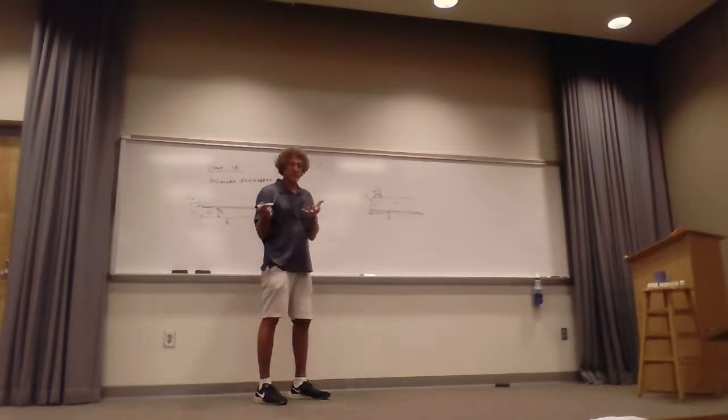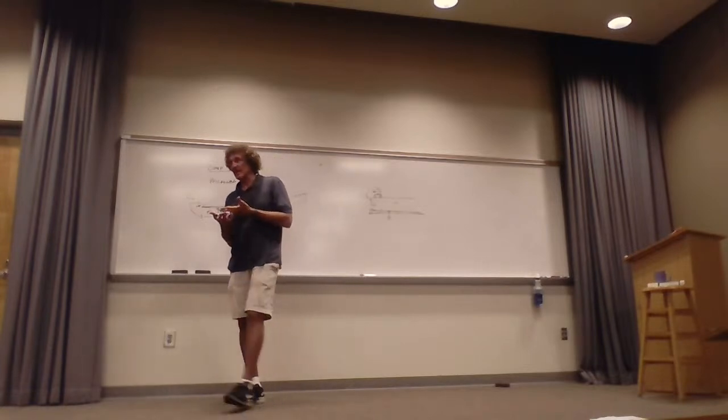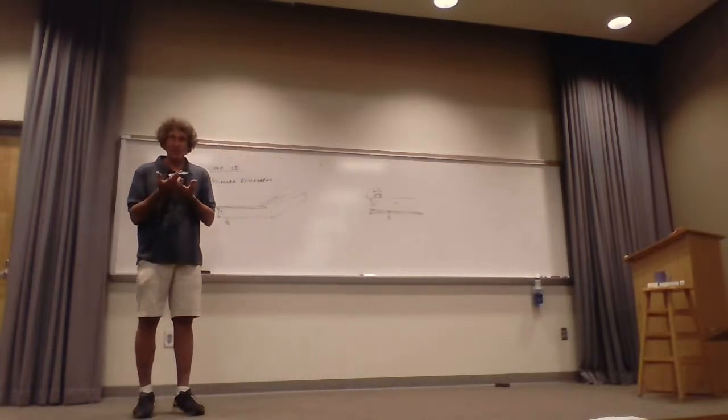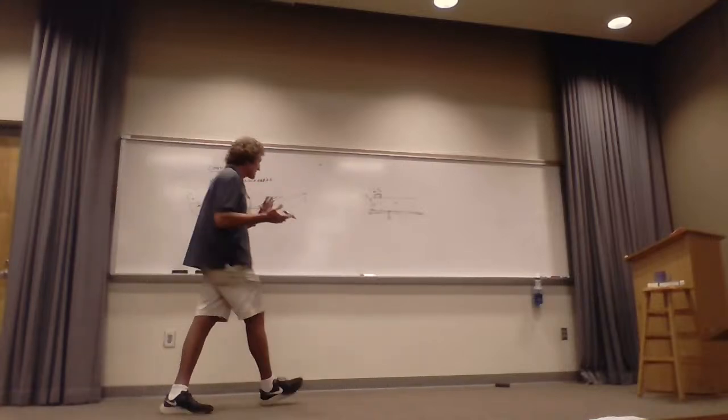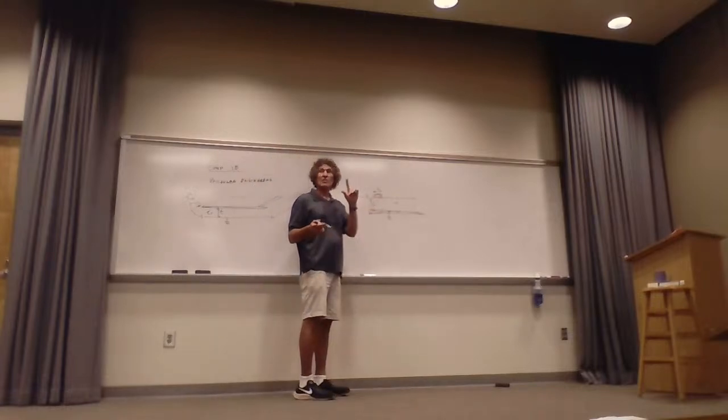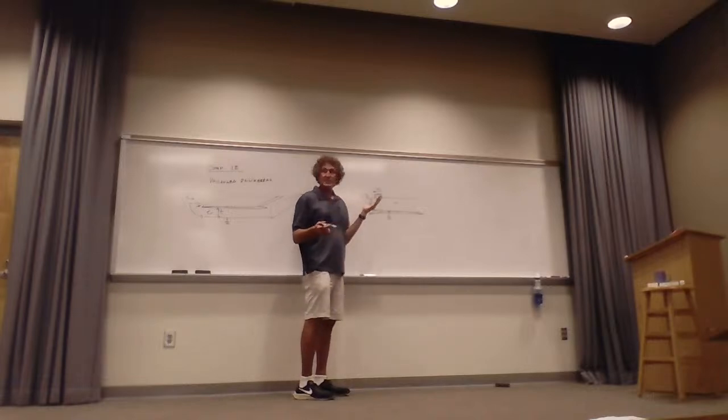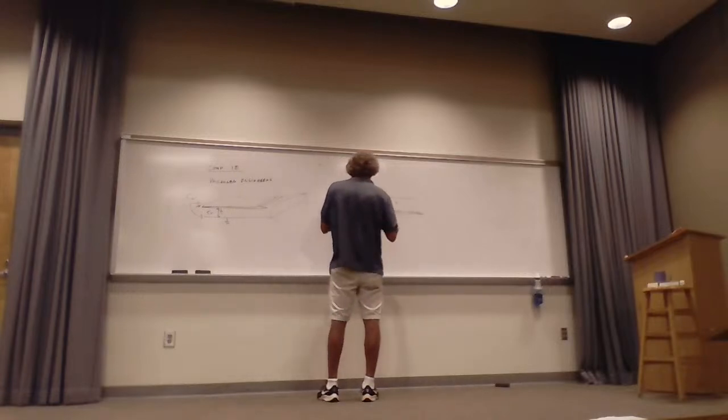What I'm doing with this microwave engineering is getting a lot of interconnects between different circuit components or antennas or transmission lines. And these lines are going to be longer than 1/10 of a wavelength, so they're actually transmission lines. Do y'all follow me? But the transmission lines are working in the TEM mode. So it's transverse electromagnetics, not a waveguide mode where the fields are bouncing around. It's all TEM mode, all right? Anyway, that's sort of the game here.